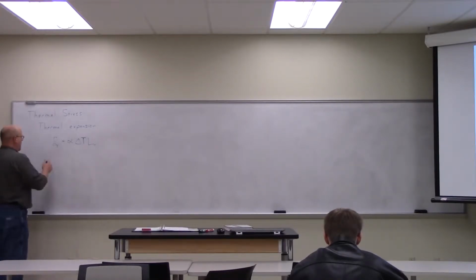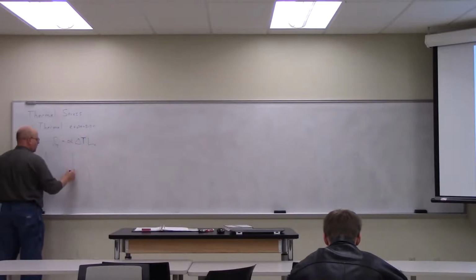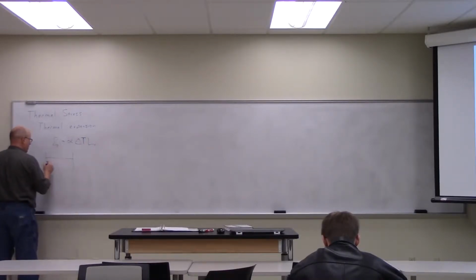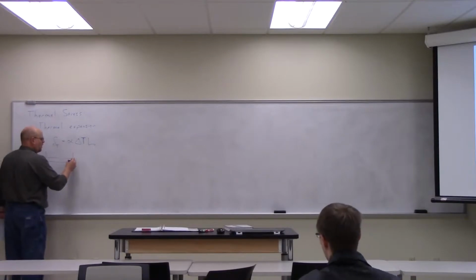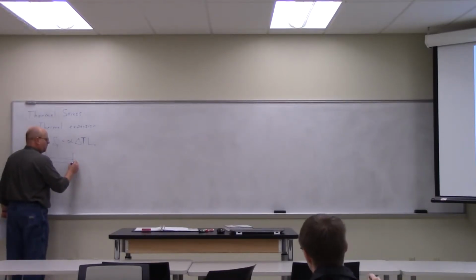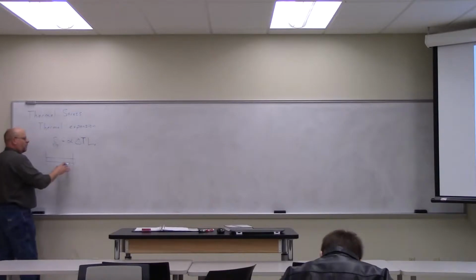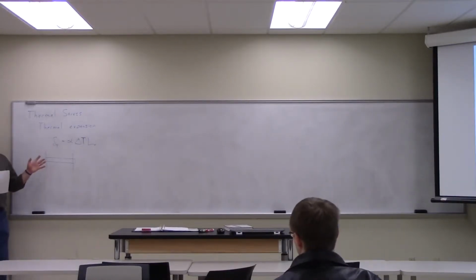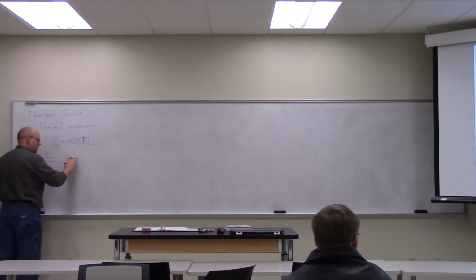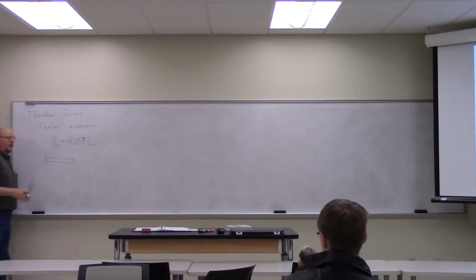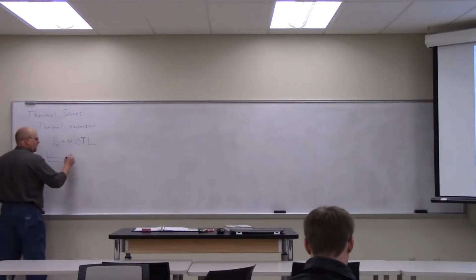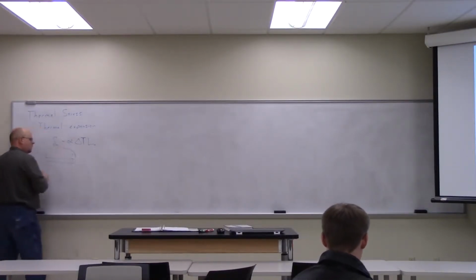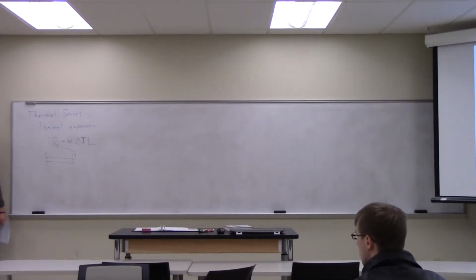constraint based on temperature. So if I have an object between two solid supports, an aluminum bar between two concrete blocks or something, and I change the temperature, as we talked about before with the concept of superposition, if the second block wasn't there, so if it's just a bar sitting out there in space, and I heat it up, it's going to elongate. And the amount that it elongates is delta sub T, thermal expansion.